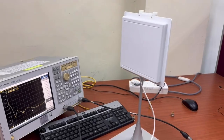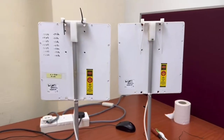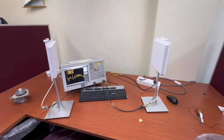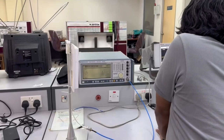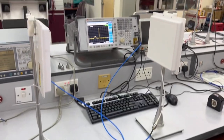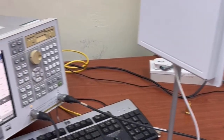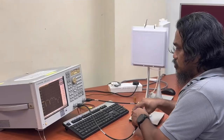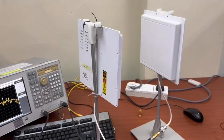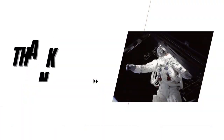In conclusion, this experiment helped me understand how RF measurement equipment such as VNA, signal generator, and spectrum analyzer work. I also learned how to set up the equipment, take measurements and observe the antenna performance and signal propagation. I also learned that as the distance between the antennas increased, the received signal power decreased due to free space path loss. Overall, this experiment improved my practical skills and helped me better understand the basic antenna and wireless communication concepts.